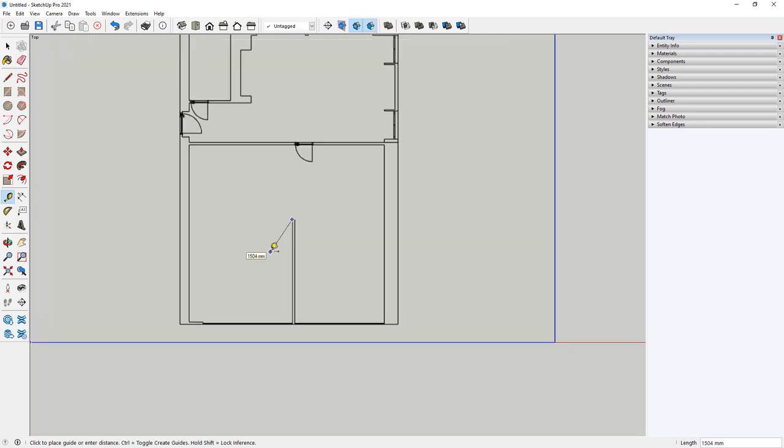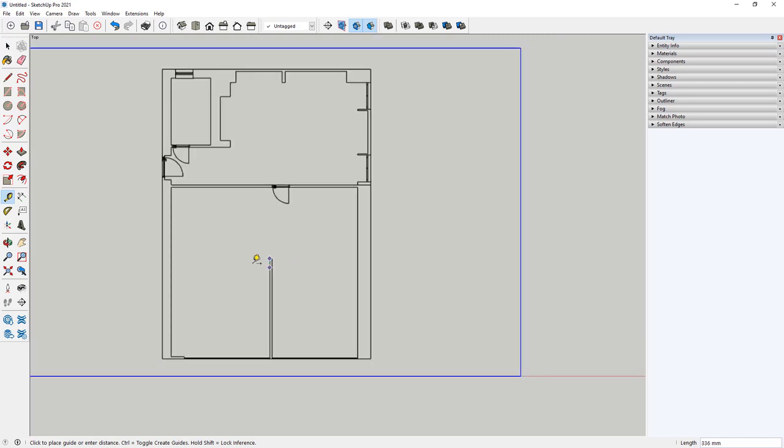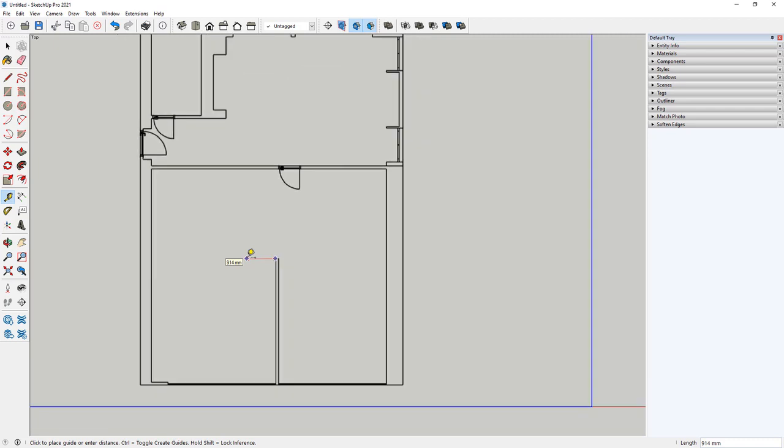So you must remember to fix most of the sizes by yourself, because a photo is not a good solution to redraw anything. This could be used only as a reference, but not to generate exactly the dimensions that we would probably get from the AutoCAD files.